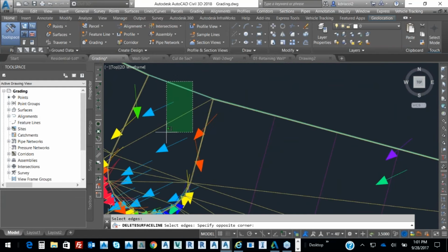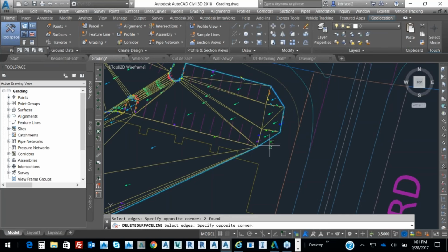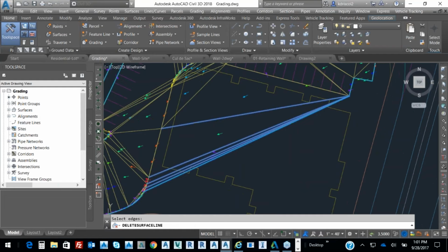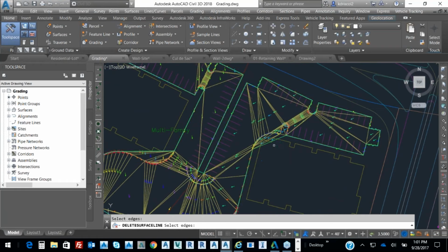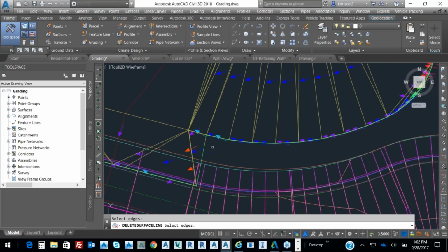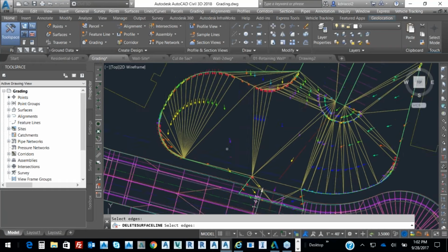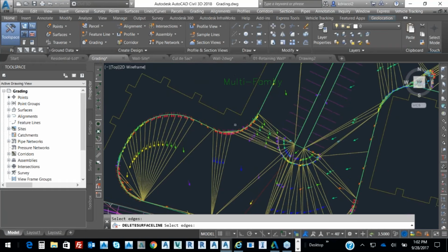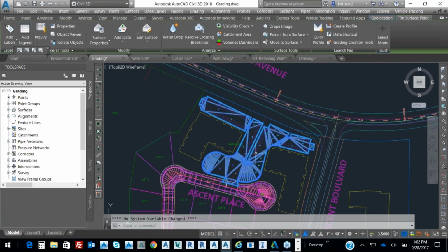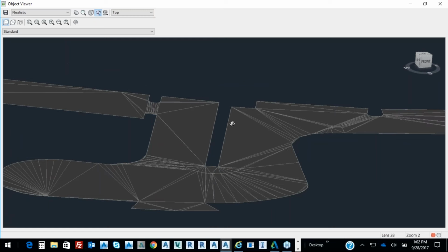We're getting detailed. This is just work that you have to do in terms of building a surface model from Civil 3D. And again, if you take a look at what I'm doing here, it doesn't take much. Just getting acclimated, and it's again the same workflow I'm using with everything that I do today. This idea of generating a surface model and then building from that. And we want to come right in here. And so that's going to be it. So I'll right click, go to Object Viewer. There's my parking lot. Pretty straightforward. Step-by-step process from the basics to the more complex.